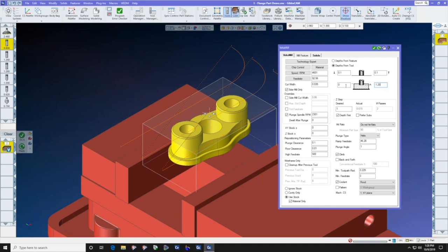Is there a way that we can get those numbers off of the workpiece? Well, there certainly is. We can double click. This is the top of the Z toolpath. We're going to double click in the top of the Z toolpath, and I'm going to alt click on the top of the part. And the dimension of the part jumped right into the dialog box.